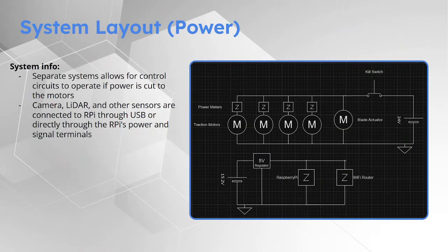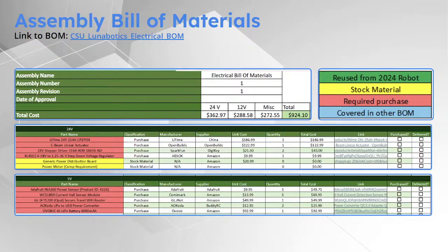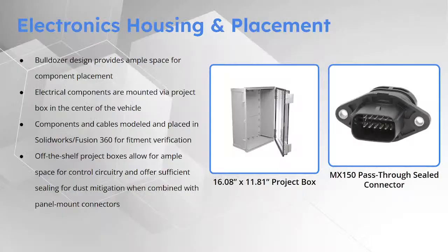We're at 24 volts. That just seemed what was realistic given what was on the market for 48 volt batteries and their price point, the amp hours we needed. Like we talked about, these motors are maybe at 2.3 Newton meters. They're not as torquey as a 48 volt motor, but with the gearbox we've got, it should be more than enough. Mechanical did spend a lot of time looking through different motors, 48 volts, 24 volts, gearboxes, things like that, and made a carefully thought out decision to make sure everything was going to play nicely and give us the amount of torque we needed.